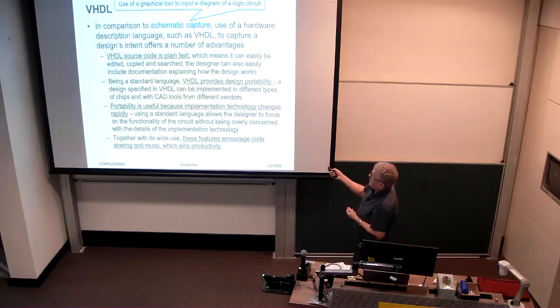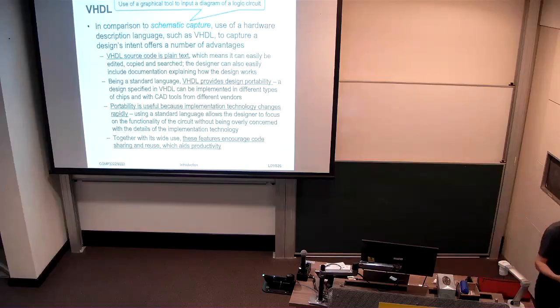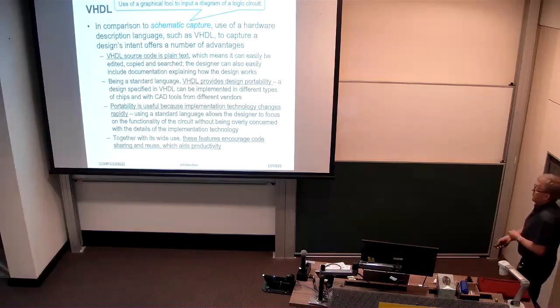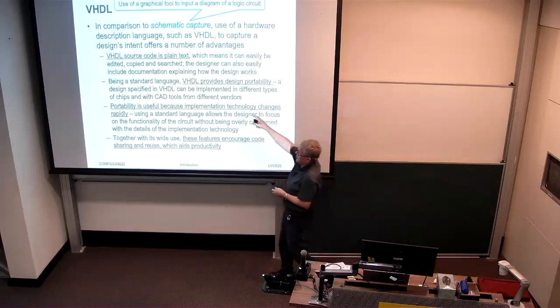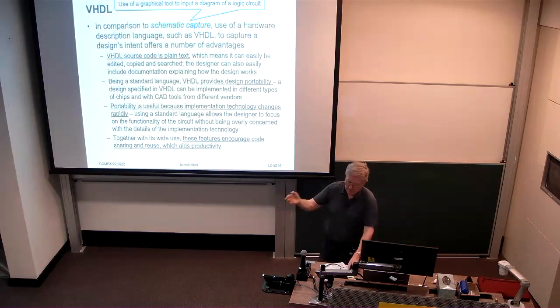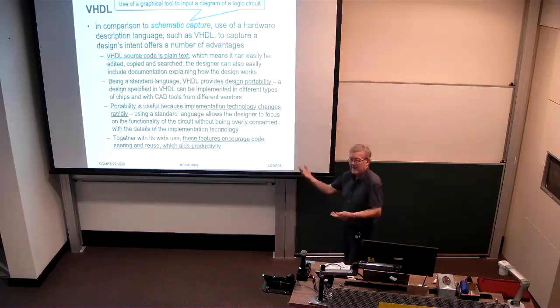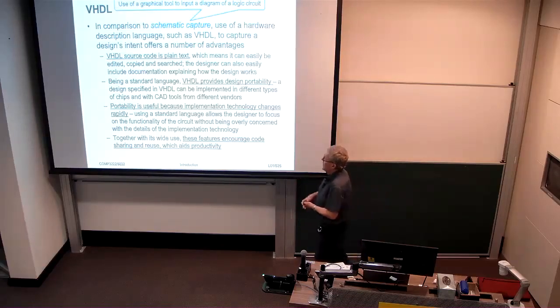It provides design portability because it's a standard language, and that means every vendor's tools will have that synthesis tool available for it. So you can take a design that's been designed for a Xilinx FPGA and port it to an Altera FPGA just by taking the code, all right? It's also important because the implementation technology changes rapidly. Not only do you have portability between vendors, but even within the one vendor, you're going to be wanting to go to the latest version of the FPGA, and that means re-implementing the design potentially.